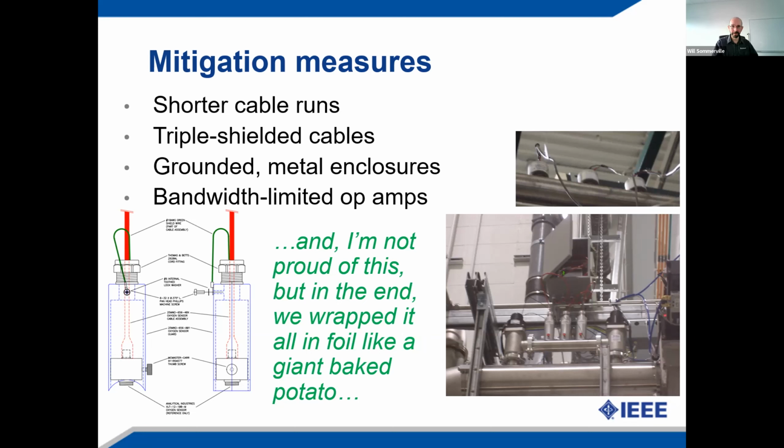So if you look at this entire area here in this bottom picture, all of that was completely covered in store-bought aluminum foil. We just caked it on several layers thick, and that is what saved our oxygen sensors from picking up all that radio frequency power and all the phase control heat, chopped up, magnetic energy that's coming out of the machine, and that's what kept the machine from hard stopping.